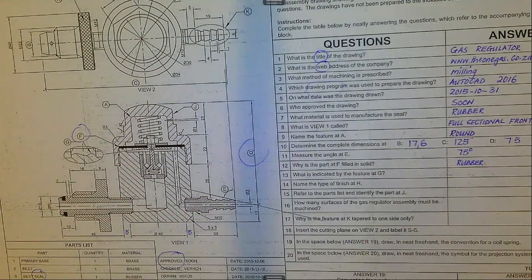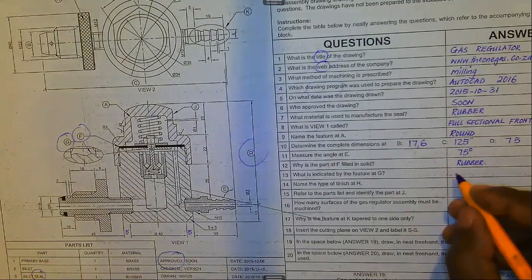What is indicated by the feature at G? So the important part is to look for G, which is here. G is representing a section. What section are we looking at? Remember, if you have got information which would normally not be shown in hatching, like a shaft, but there is certain detail that you would want, which is inserted into a shaft, say you have got a key which is inserted, so that you expose the detail which is inside, we refer to that kind of section as part section.